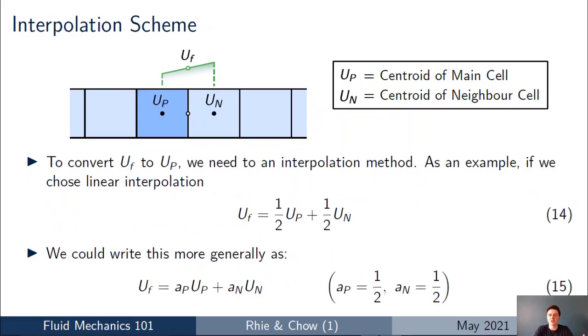And it's at this stage where there's actually a bit of flexibility in the finite volume method. And this flexibility is passed over to the user, where the user will often get to decide in the CFD code what method they'd like to calculate the values at the cell centroids from the values at the face centers. This is often called an interpolation scheme or a discretisation scheme. And if you've watched my videos before on upwind differencing, linear upwind differencing, you will have come across this concept before.